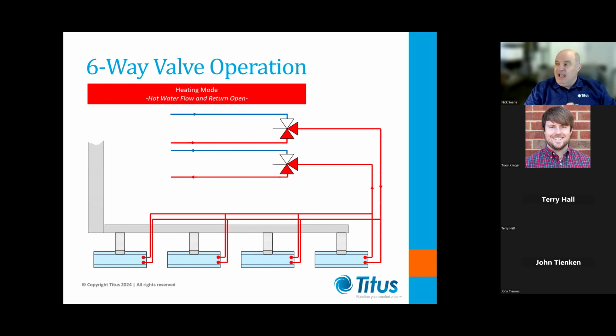Now, one of the primary considerations you have to think about if you're considering using 6-way valves is water treatment. What you'll notice through this setup is that the water mixtures between the hot and the cold side must be the same, because they will mix. So if I run through the cycle again, let's say you've got glycol running with the chilled water. So what we're going to do now is go through this cycle of cooling. We're pumping chilled water with glycol through the chill beams. And then as we go through to the deadband, we've still got glycol in the circuit of the chill beams. And then as we switch over to the heating, you'll see that the glycol that was in those chill beams from the chilled water will pass back through the return of the hot water.